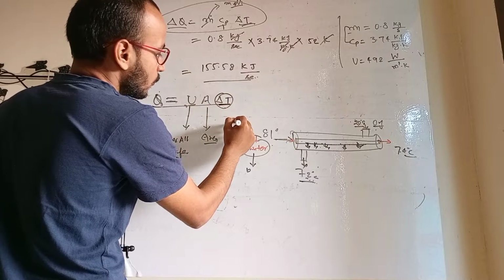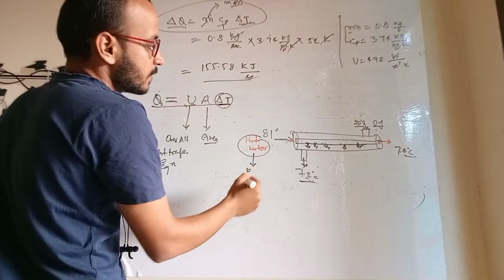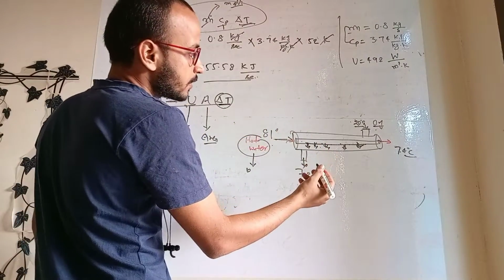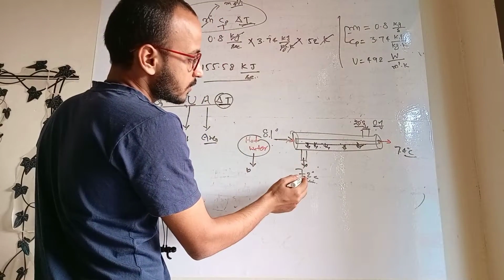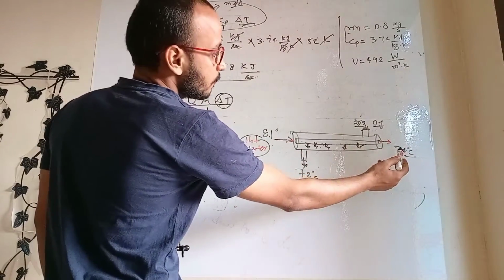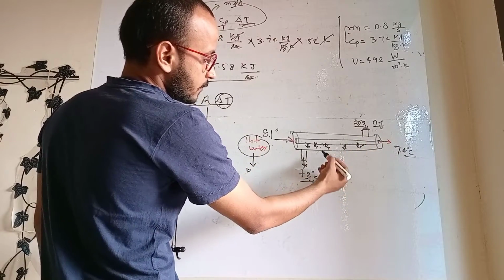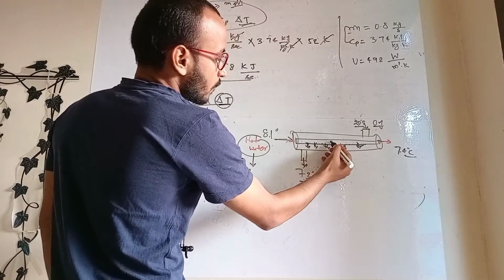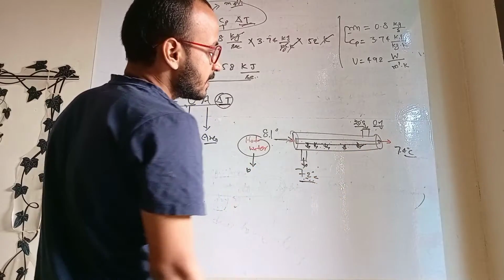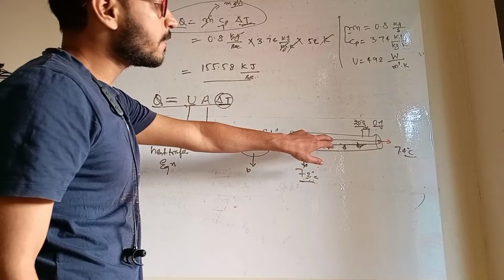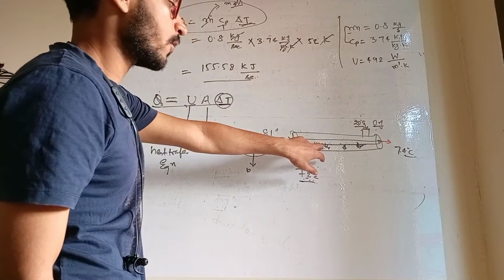Okay, here the major problem comes: when we talk about delta T, it is the temperature difference between the hot and cold points. But what is the temperature difference between hot and cold? Would you say 81 minus 72? No. 74 minus 72? No. We can't say that, because at each point the hot water temperature is different and at each point the cold orange juice temperature is different. So we cannot simply subtract the temperatures.